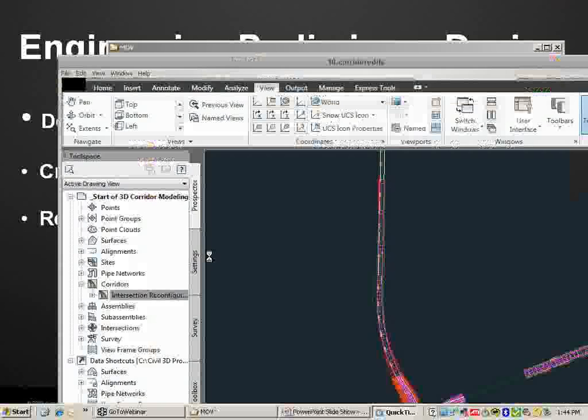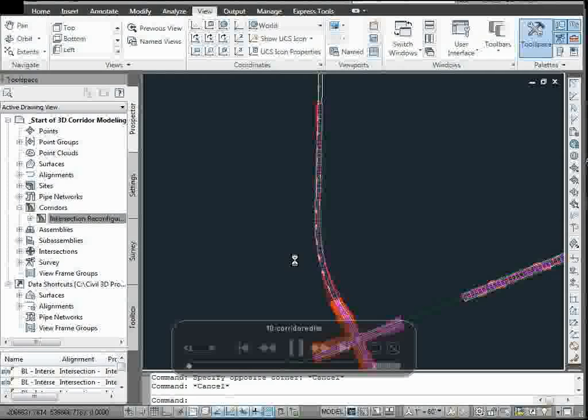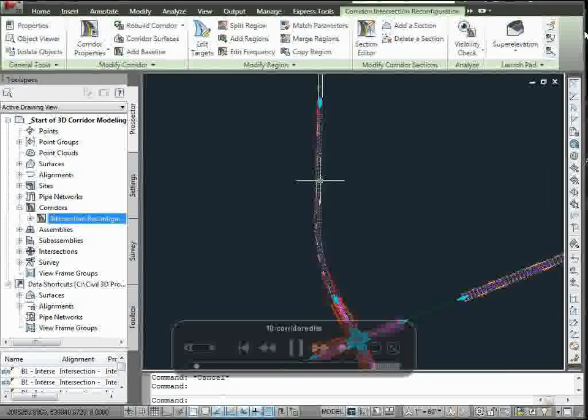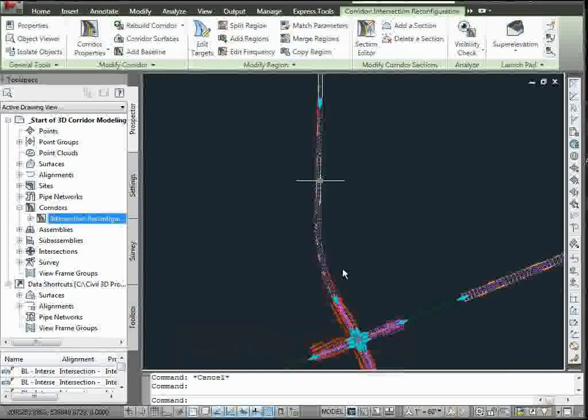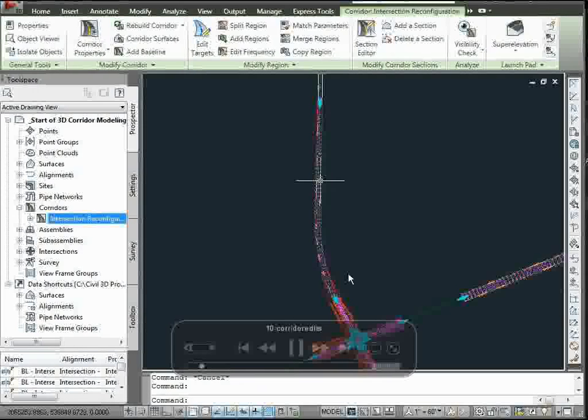Now, this is where you want to make some edits quick. We've already done this corridor. This is the beauty of that dynamic model that we talk about. We've got the corridor built, and I'm going to give you an example. What you're going to see here is one of the things as we get in here, like in curves, if you get into machine control and you want to dump out all these sublayers to machine control, one of the techniques is that you want to densify the machine control section.